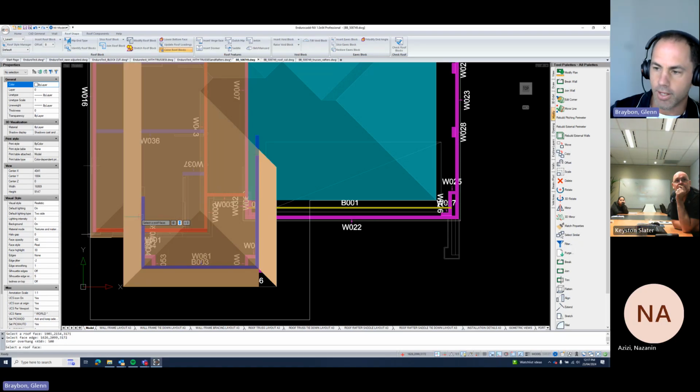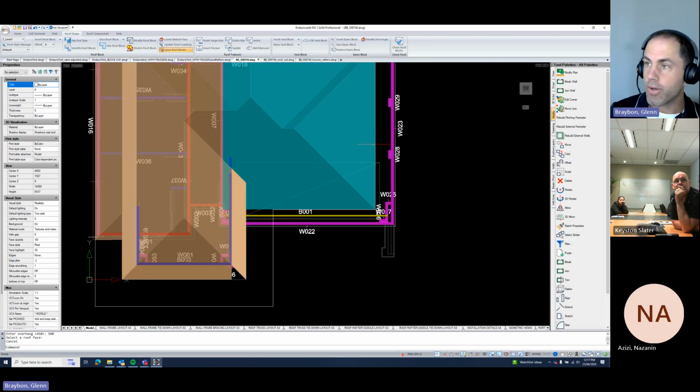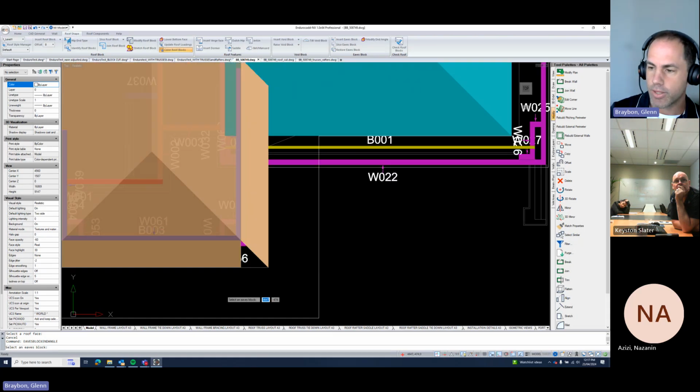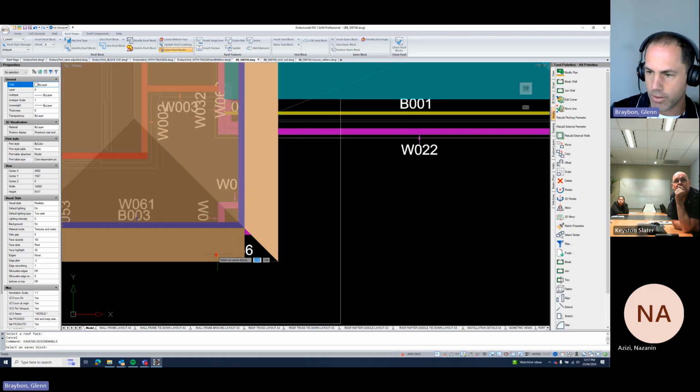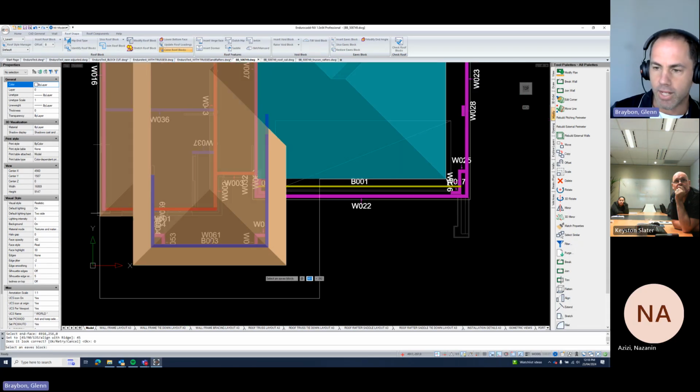Okay, so we've got a couple of issues here, obviously. We've got this big long eave here. I don't think EnduroCAD does that. Obviously, I'll speak with our programmers about that, but we do have the ability to modify the end angle. Not 100% sure why that one didn't work. I think it did when I tried it before, but if we do this, select here, 45. Does this look correct? That should be a yes, not an okay. But we can modify the block, modify the eave angle.